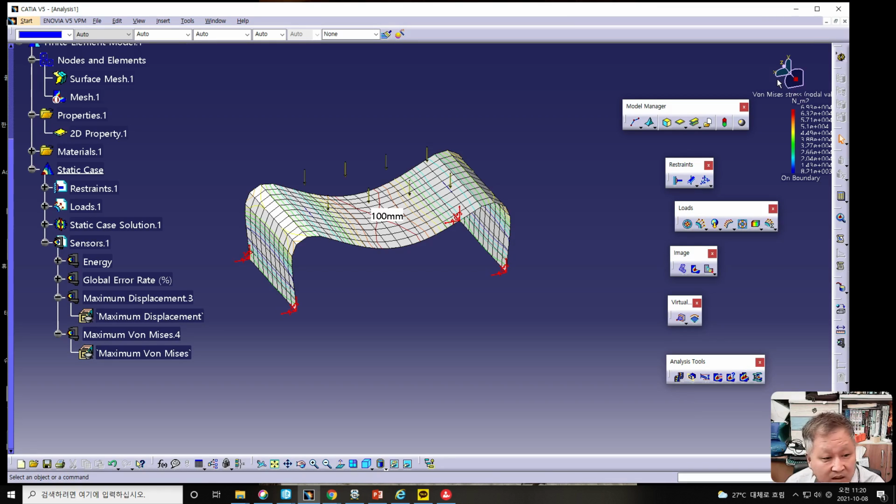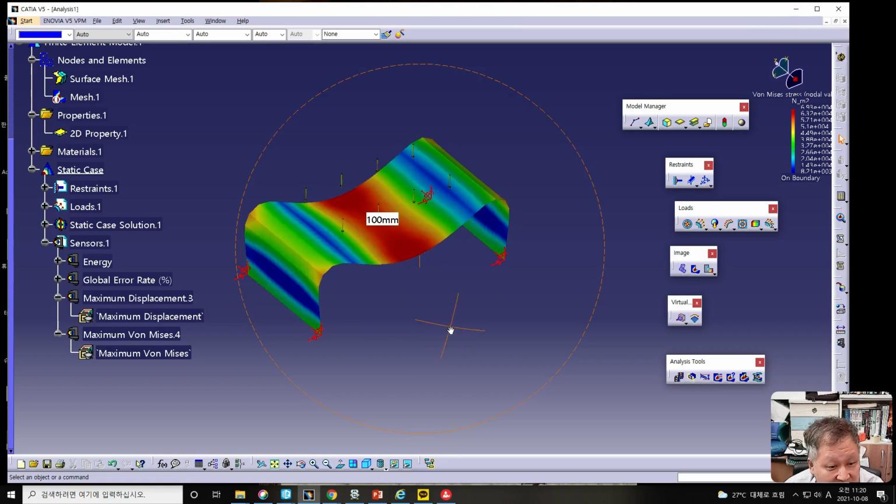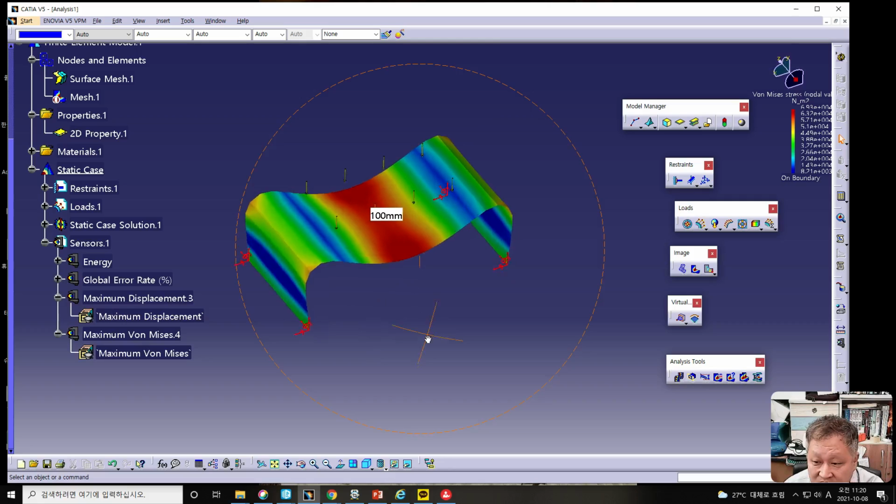Hide the previously created deformation model and change the display type in various ways. If the view mode is this, as shading, please change the view mode to shading, maybe shading with material. Then the view mode is changed like this, and the following figure is shown.